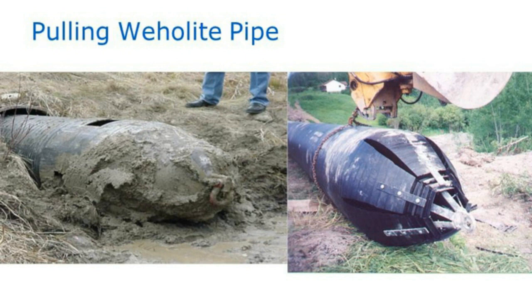These can be fabricated in the field by the contractor by simply cutting out wedges of the pipe, bolting on some type of strapping apparatus so that they can cinch the end of that pipe down and create that bullet nose on there. And then with that, generally, if you can see in the slide to the right, that should have a hitch type connection on it. They're able to attach a cable to that and then pull the culvert through the host pipe that way.